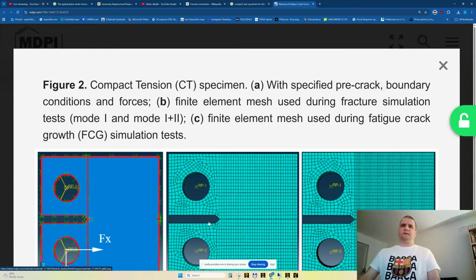You can say, for example, that the notch is finished here, but no. It has an additional, supplementary, very acute angle groove, or we call it the crack initiation area. And you can see it further here, even though it's very small.